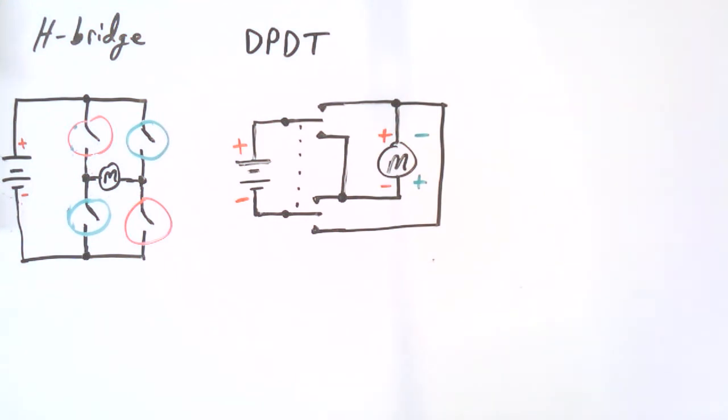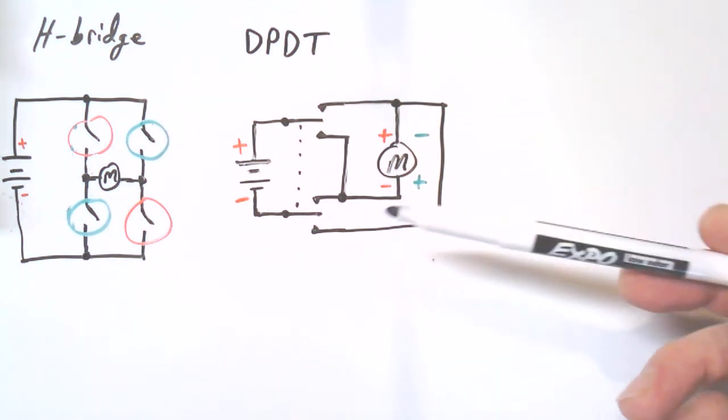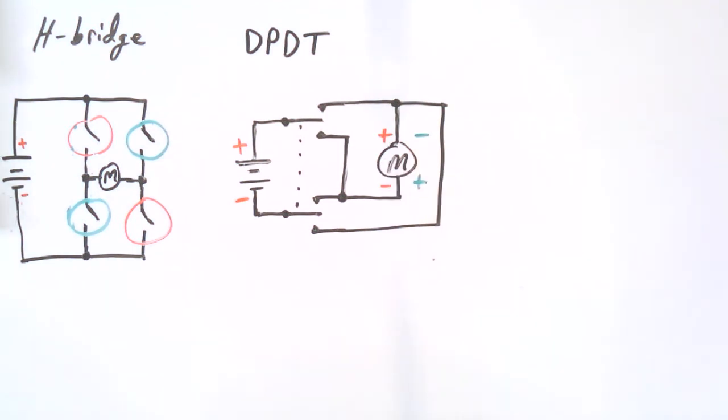You would need other things to add to the circuit so that it doesn't just slam from forward to reverse. I mean, believe it or not, some motors can handle that, or some devices too. But if you need that off position, you'd have to add some more to it. But yeah, they can be relay contacts as well.